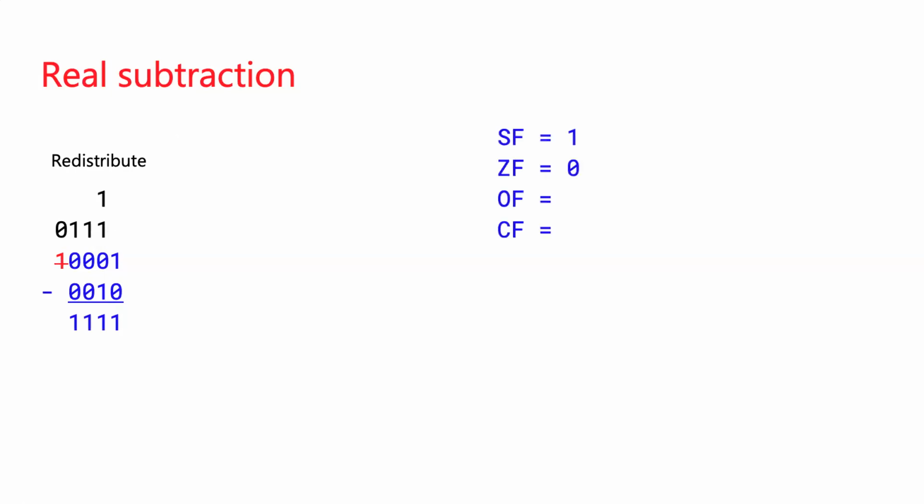The 2 up there minus the 1 gives us 1. And then these 2 remaining ones, each of them minus 0, gives us a 1. So that's the result. If you thought of this as a signed value, well, the overflow flag reflects signed overflow. That's what we call V in ARM. And we didn't get a signed overflow because just reading them as numbers, 1 minus 2 gives us -1. And sure enough, that's what we got. So the overflow flag would be 0 after this.